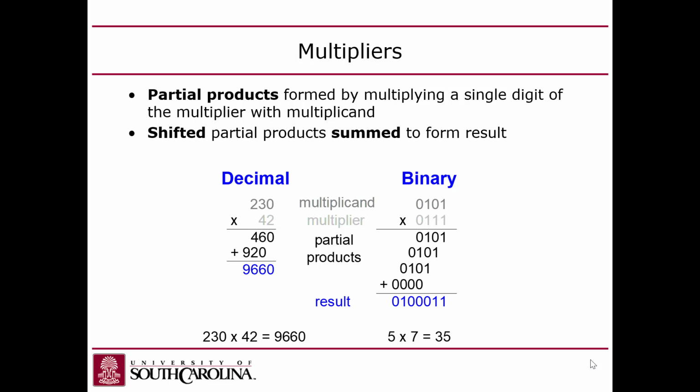So this 1 bit here is in bit position 0 of the multiplier, right? So this means I want to shift by 0 bits, because the 0 bit is turned on in the multiplier, and the 2 bit is turned on in the multiplier, right?